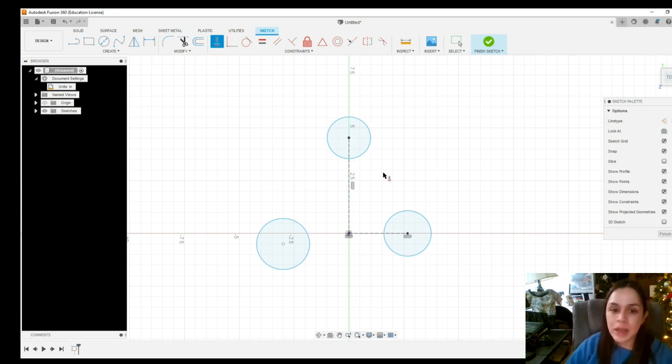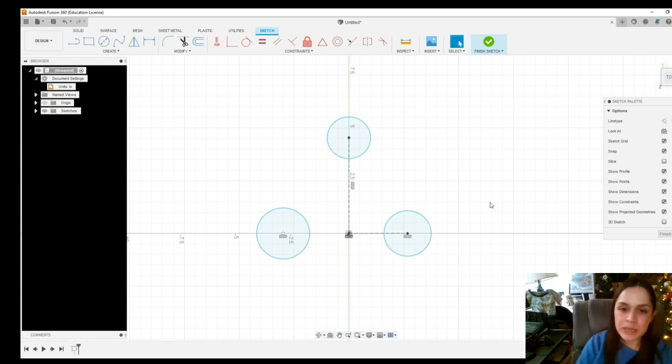But then you don't need a line at all, and this is what I'm going to demonstrate here. I'm going to left click on my origin and then left click on the center point here, and notice how they're all in line with each other. So that's exactly what I'm doing, is trying to center that circle. I'm going to press the escape key to get out of that feature.